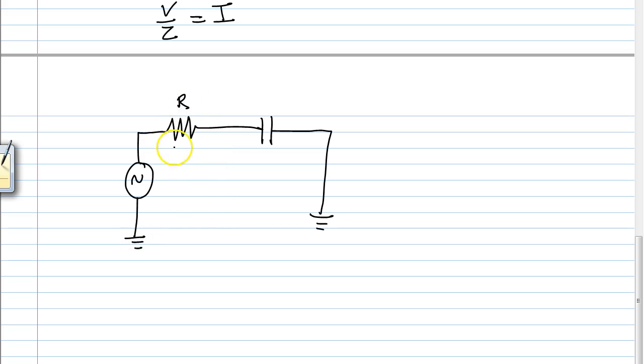Now the resistor is 2.2K, and the capacitor is 0.022 microfarads. All right. Now it tells you that the voltage source is 10 volts at 0 degrees. Notice that it gave you the voltage in polar form. That's key there. And also, the frequency is equal to 1.5 kilohertz.